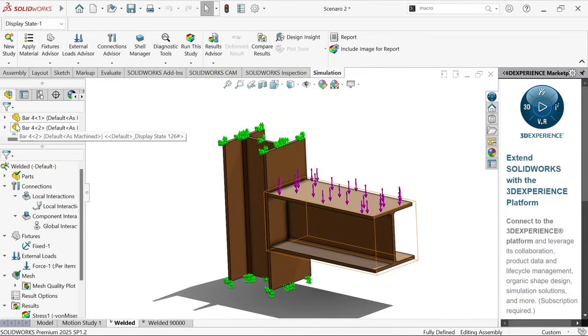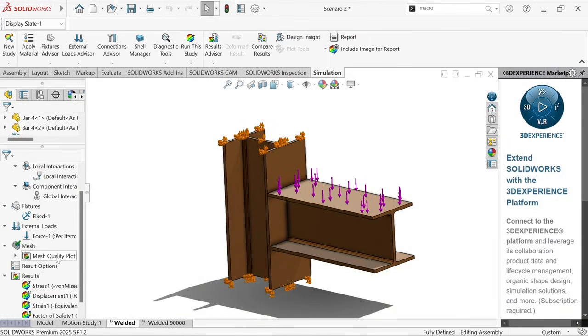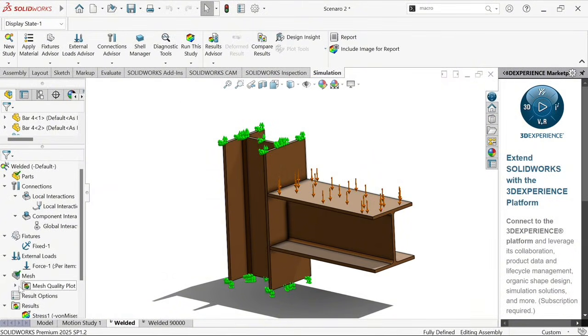I will now be having the options, because when you try to mesh, since we're not trying to pay attention to the stress exactly at that point, right? We're not trying to check the stress for the weld beads themselves, since we couldn't model an extrude boss base for the weld beads and mate them there, which is going to take a lot of time, and when it comes to meshing, it's going to make it a bit difficult. Okay, good. Now, straightforward, we go to meshing directly.